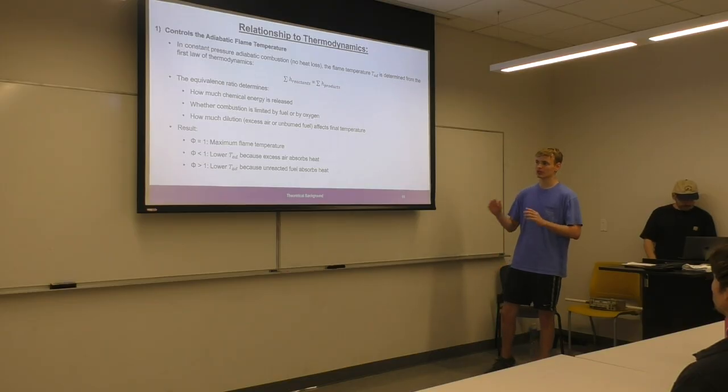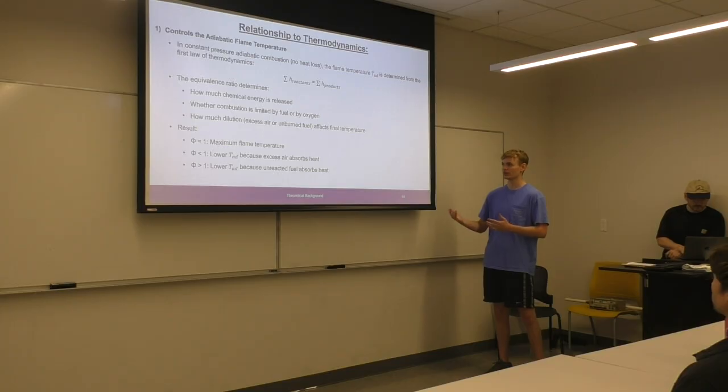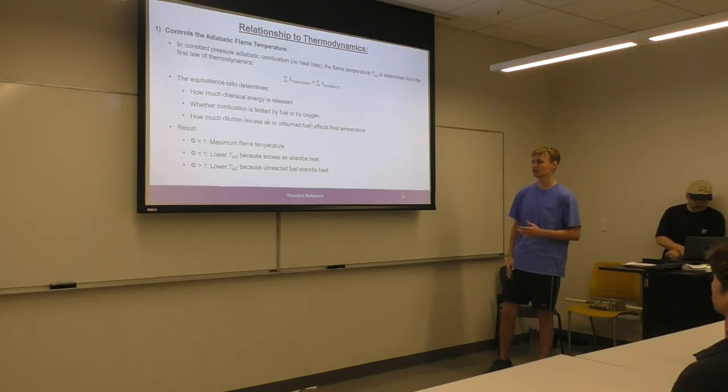So the result is, at stoichiometric you're going to have your maximum flame temperature. If the equivalence ratio is greater than or less than 1, you're still going to be lower, because of the excess air absorbing heat if you're burning lean, and if you're burning rich, more unreactive fuel absorbs the heat.